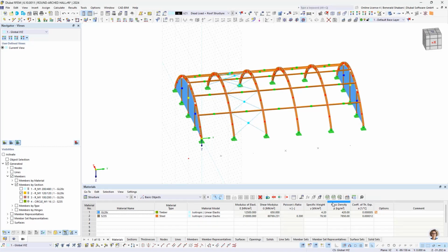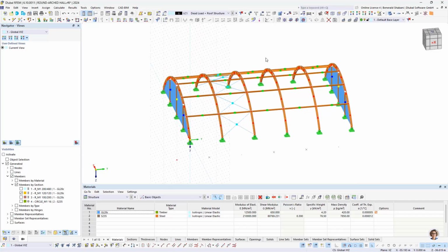I figured that from truss to truss there would be trapezoidal profiles, like sandwiches with insulation on top and a foil roof. I assumed it will weigh about 30 kilograms. Of course, the dead load can vary from hall to hall.